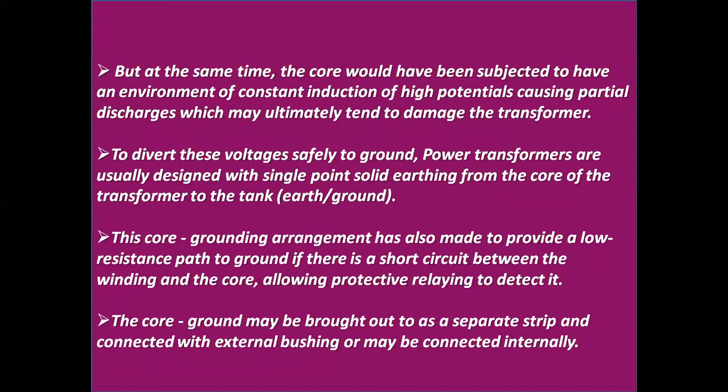But at the same time, the core would be subjected to an environment of constant induction of high potentials causing partial discharges, which may ultimately tend to damage the transformer. To divert these voltages safely to ground, power transformers are usually designed with single point solid earthing from the core of the transformer to the tank or earth or ground.